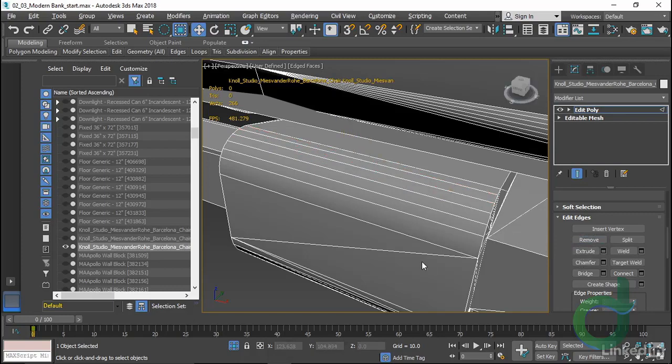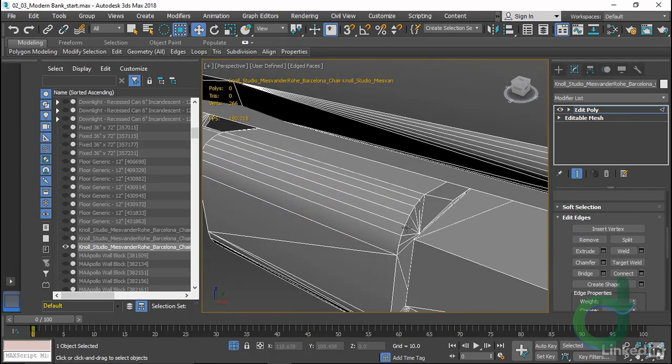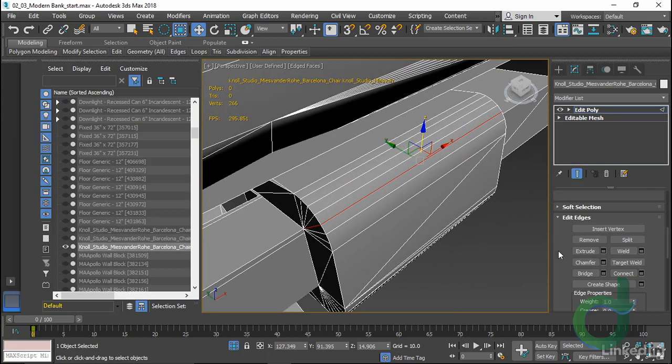And now I can look at taking out some of these facets. What I'll do is to start to take out every other one. Double-clicking on that edge loop, 1 up, 2 across, and 3 down. And now doing a clean remove, holding Control and clicking on Remove to remove the vertices.